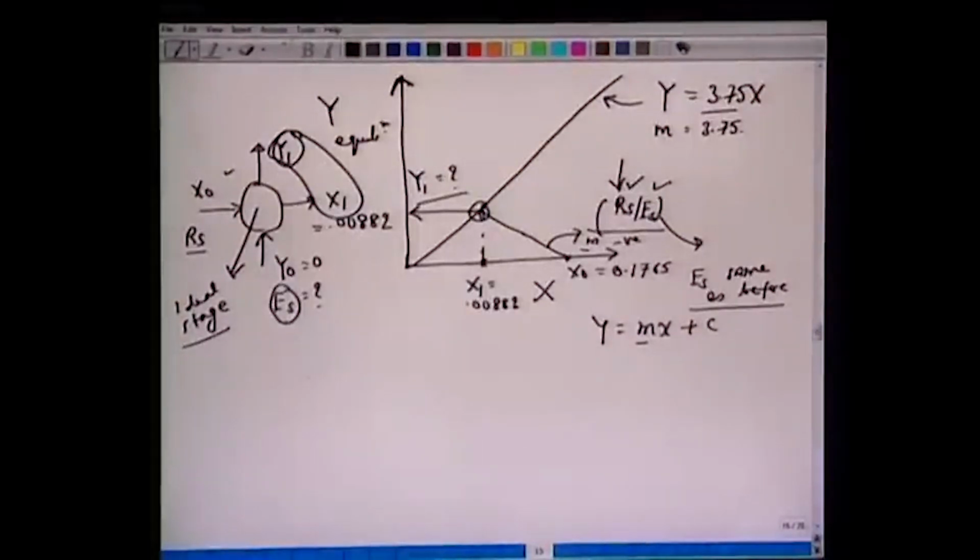Now, let us get to the second part of the problem, where it says we have taken 3 stages. Okay. So, now we have one stage, two entering streams, 2 exit streams. We bring it in contact with the second stage. Now, in the second stage, again we add a fresh feed. Again you treat it as an ideal stage, the 2 exit streams are in equilibrium, take this treated stream from the second stage, bring it to the third stage, and there again you bring it in contact with the fresh fluid.